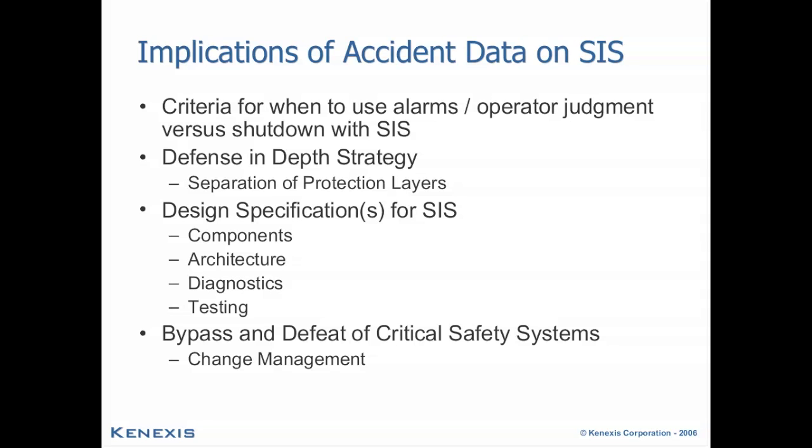We see a lot of these accidents that involved improper design specifications for safety instrumented system components, or the overall architecture is not provided with what we call a fault-tolerant architecture, or there's improper testing and diagnostics of components in those designs to ensure that they work and are robustly tested on a regular basis. And I have to say, with great regret, not only in the past but even recently, we continue to see incidents that involve operator bypass and defeat of safety critical systems.